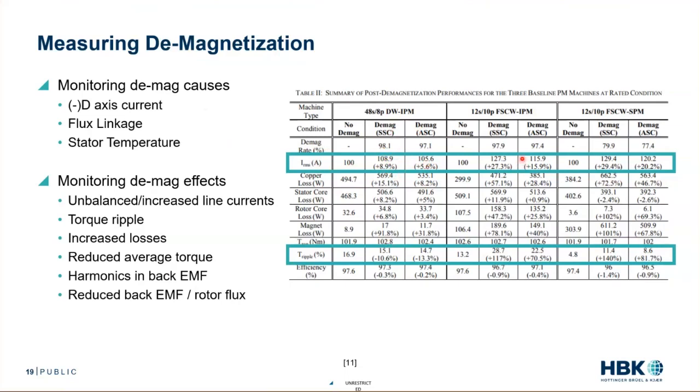And then we go to the different winding configurations, and now we see plus 30%, plus 30%, plus 20%. So these are very notable things to make the same torque. We could also see torque ripple. We have an increase or a decrease of 10% of torque ripple in this given configuration. We have an increase of 100% and 70% of torque ripple in these other 2. These are things we can pick up on really easily from a measurement perspective.